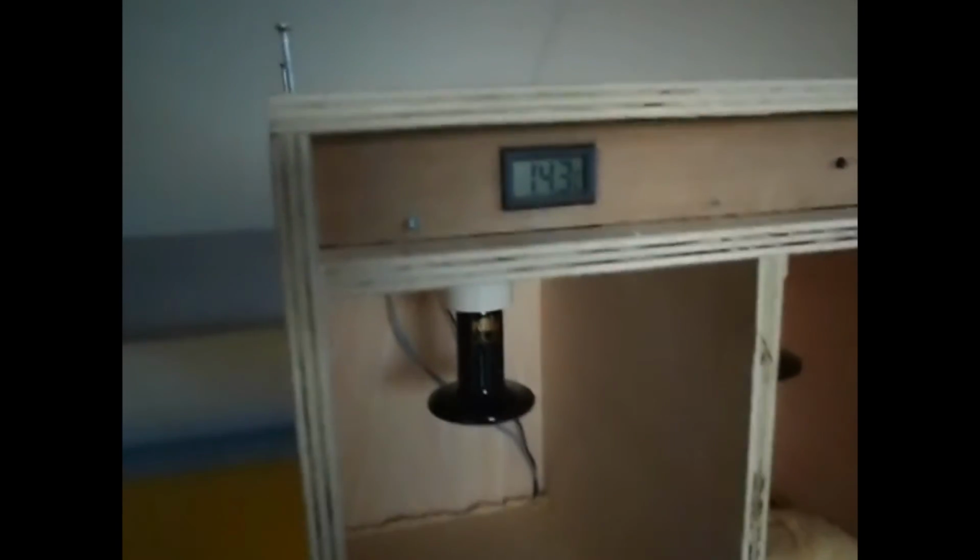It's 8 centimeters all around, and on the inside there is a hollow room, and we put a temperature sensor on the inside. Here the wire goes up, and then here is the readout, so we can see what the temperature in this small room on the inside is. And we did the same for glass wool, and here is the polyurethane.